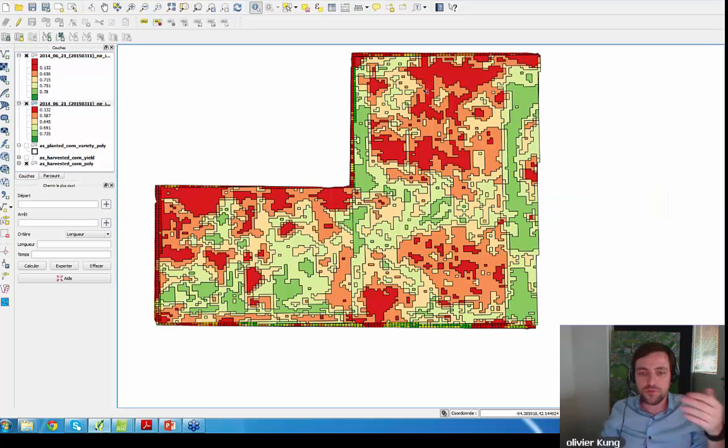If you take this shapefile and import it in your tractor console, it's going to load it and then ask you which column is the rate. That's where you select in your tractor console the rate for this particular value, and you can directly start spraying with the different rates. Also, normally the console will ask you, as I just said before, what is the unit of the rate you want to apply.